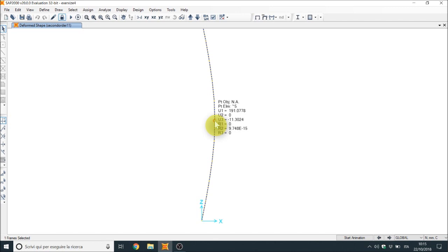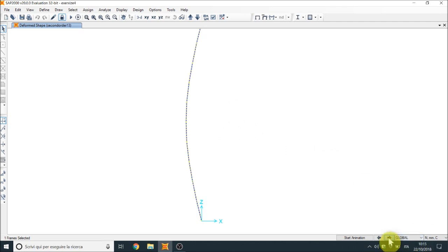And this is what I expected because the buckling mode is 11.6 and now I amplified by 11. So we are in the plateau. If I put 12, you can see that the displacement is changed. Change the direction. And became minus 94. So it's something like this.